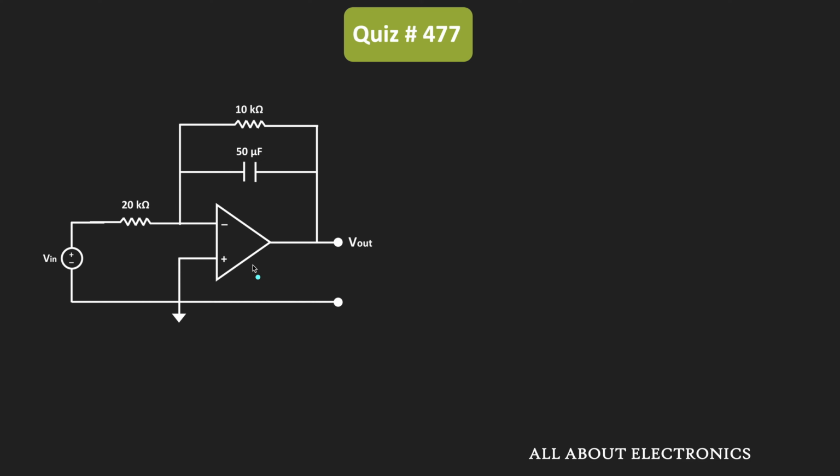That is why, when we do the Laplace transform of the given circuit, in the equivalent S-domain, the op-amp will remain as it is. Apart from the op-amp, the resistors will also remain as they are. Similarly, the capacitor in the equivalent S-domain corresponds to 1 divided by Cs, because we are assuming that the initial conditions of the circuit are 0.